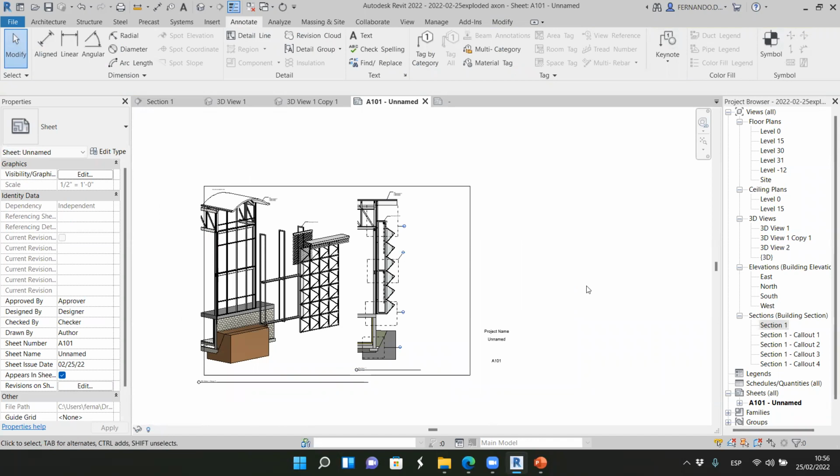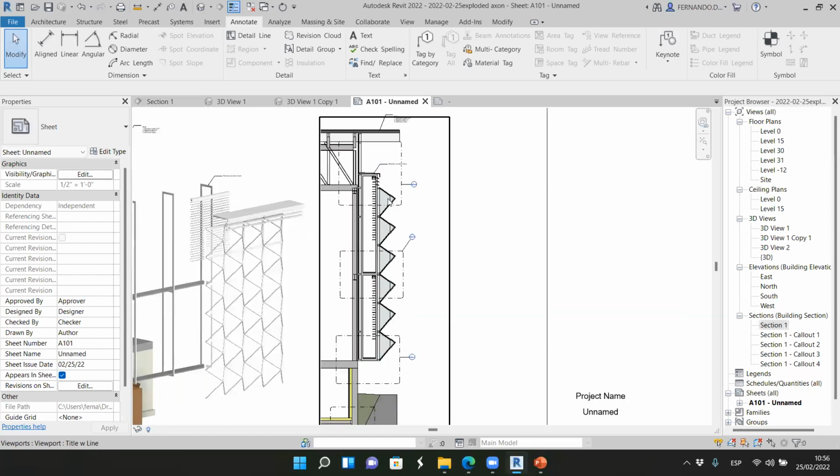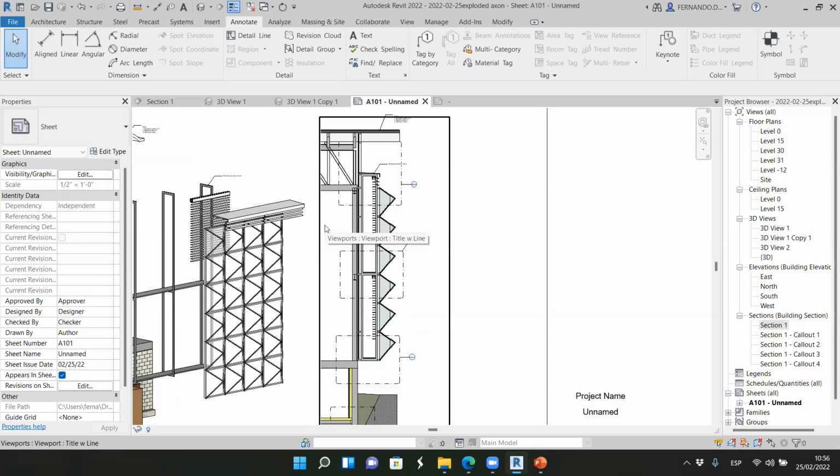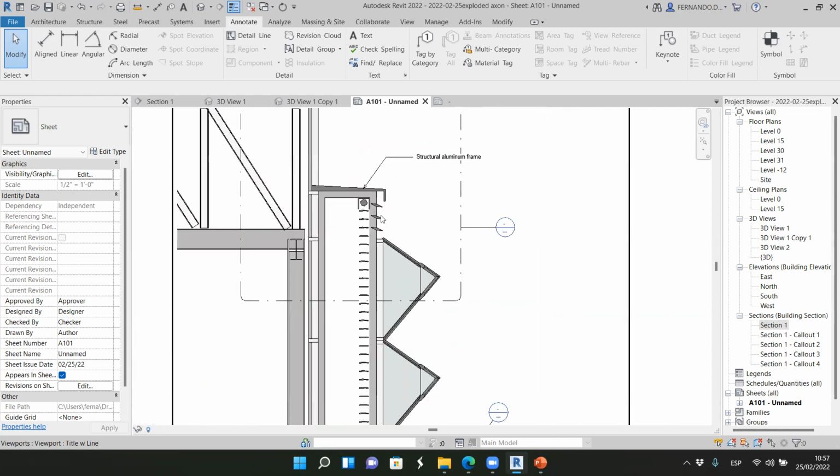And finally, we can work with callouts. So I think last Friday we worked with this callout. We tried to solve the roof, the curtain wall, the truss, the steel structure. Now we can make something even more appealing, and we're going to work with a callout, but just defining this element.